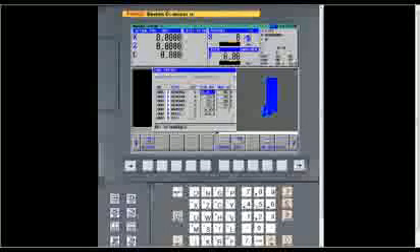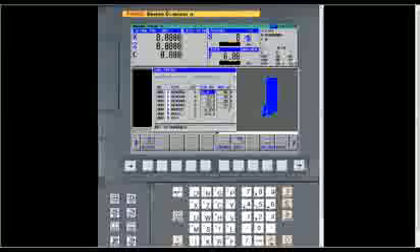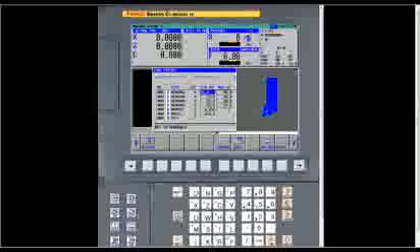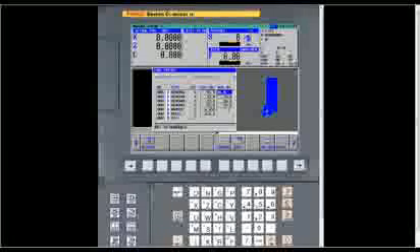All right. Now the next one, cut angle and nose angle. These are very critical, because if we put the wrong information here, you get all kinds of bad information when you actually make the program. As I said, the tool that I have in my machine is an 80-degree diamond tool. And with that type of tool, it always has 5 degrees of clearance on the front side. So if it was perfectly square, it would be 90. So you take 90 and add the 5 degrees of clearance, and that's where you get to 95. Then the nose angle is the actual shape of the insert, not the clearance relief on the backside, but the actual shape of the insert.